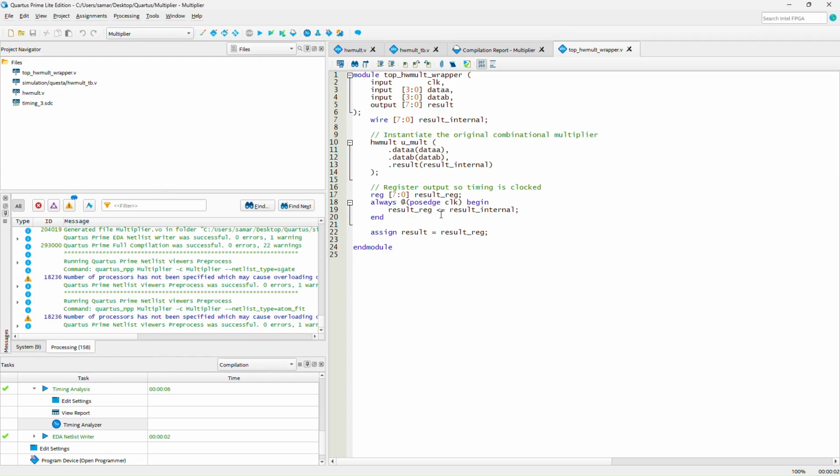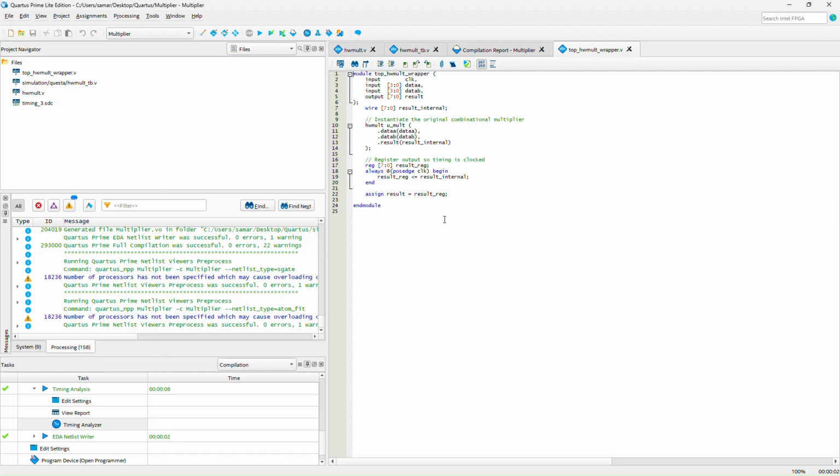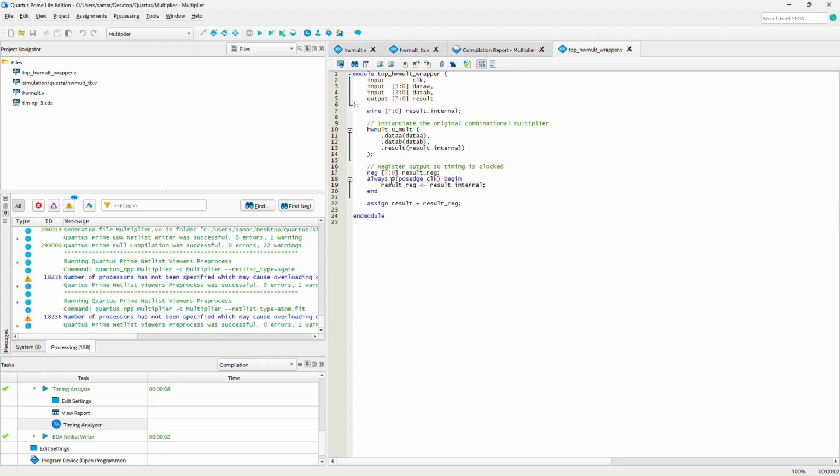This will be more accurate as it is not a virtual or pseudo register. We are actually creating the registers, and to know the accurate timing, you would always measure the time from one flip flop to another flip flop to get more accurate results. So this is another way to calculate more accurate results if you'd want.